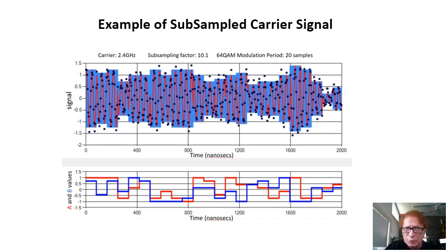The new algorithm will be able to treat such arbitrary sampling patterns and to predict the statistics of the A and B estimates, and in turn will select a preferred QAM constellation, and then the number of bits per symbol become available. We must say something about the noise measures that we will be using here.